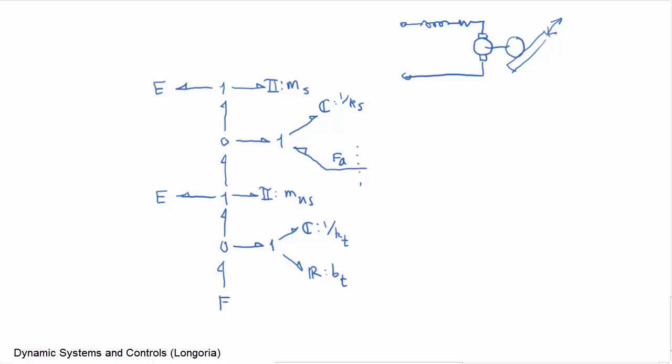And so here you can have a gear connection, and you have a rack and pinion combination, so that you have a rotation-translation conversion here. And that's the actuator that you would have here. The actual devices that were built at the Center for Electromechanics used a different kind of motor, not a permanent magnet DC motor. They use brushless DC motors. There's also some damping in here.